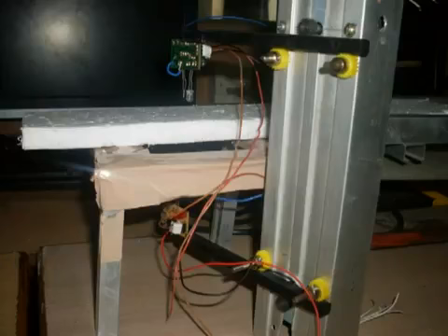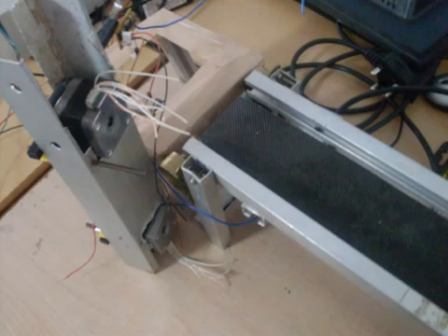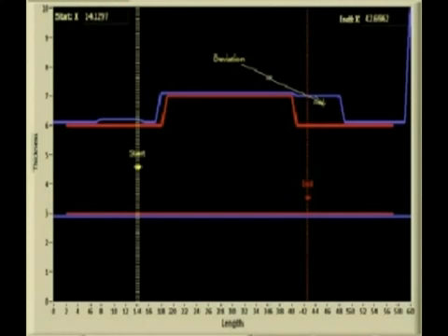From the IR sensors the continuous voltage will be obtained. The equivalent of the voltage will be calibrated as a distance in the LabVIEW programming, where voltage is proportional to the distance by means of calibration.